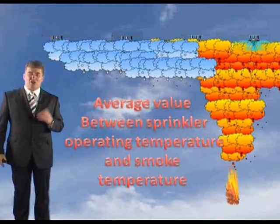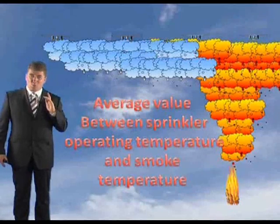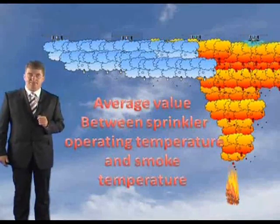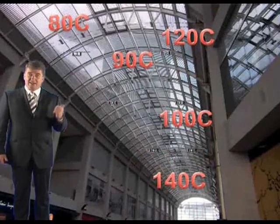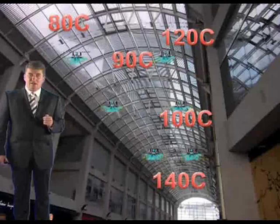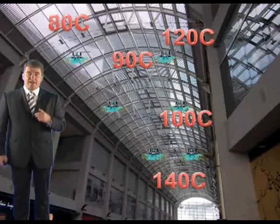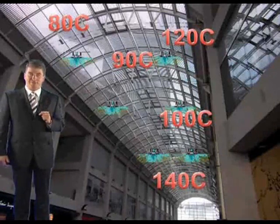Now, a fire may occur close to at least one of the extract openings, whereas the other openings may be well outside any probable zone of operating sprinklers. Now, if the sprinkler operating temperature is set high enough and is above the calculated smoke layer temperature, then sprinkler cooling in the smoke can be ignored. So it's not going to go off anyway. If the temperature of the smoke is well below the operating temperature, they're not going to go off unless there's actually a fire in the atrium itself.